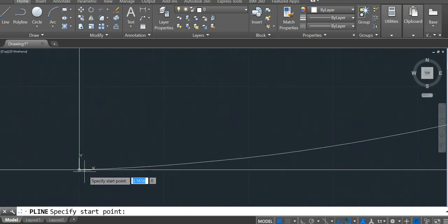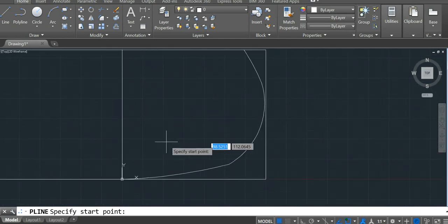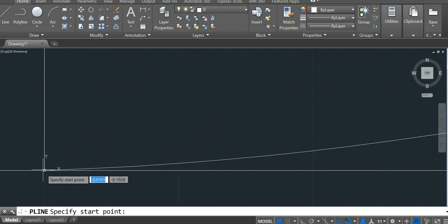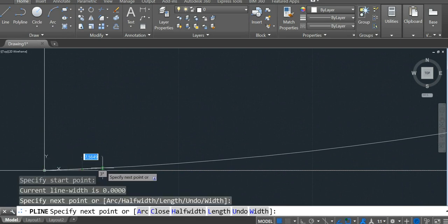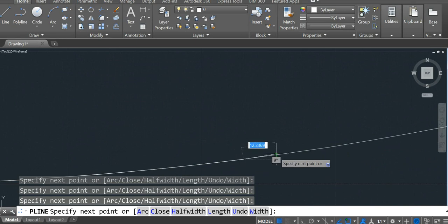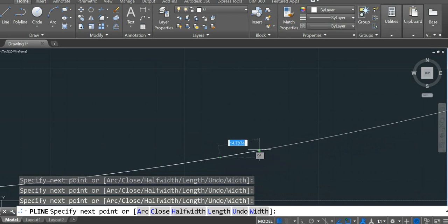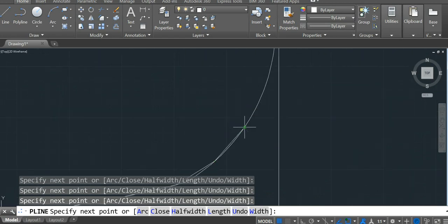You need to try to make a bunch of tiny little chords along the line, because we're going to output this line to Excel and it's only going to pick up the end points. So the shorter your chords, the more accurate your shape is going to look in Excel and the Delftship program that we'll be using. So just do a bunch of tiny little chords like I'm doing here. Hopefully you understand what I mean. Anyways, take your time with it, but I'm just going to speed it up here just so I can show you.